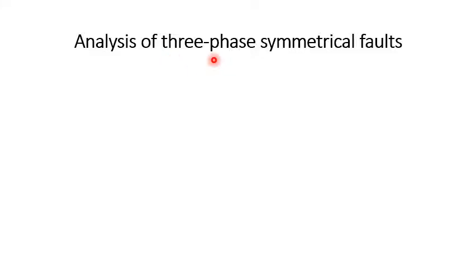Next concept is analysis of three-phase symmetrical fault. The symmetrical fault can be analyzed on a single phase basis using the reactance diagram. The fault analysis has to be performed separately for the subtransient, transient and steady state conditions of the fault, because we know that the reactance and the internal EMF of the synchronous machine will be different in each state.